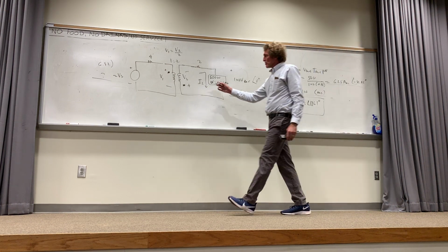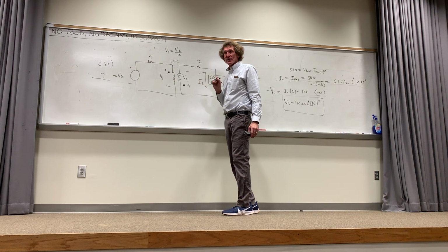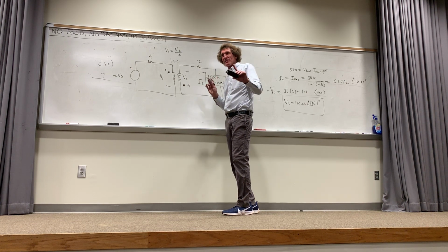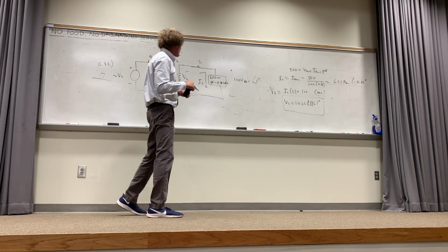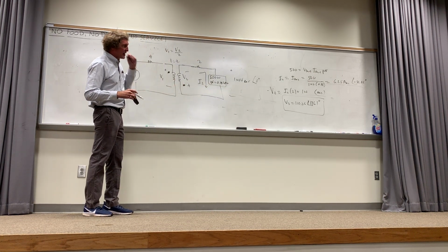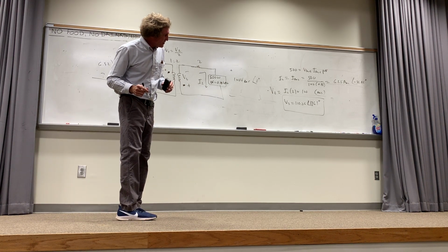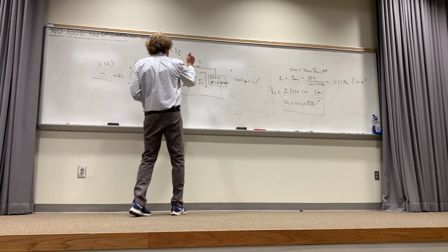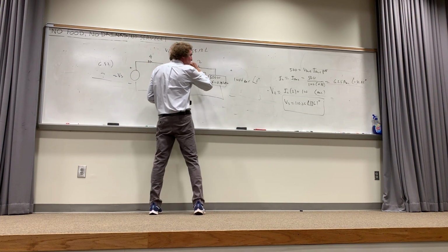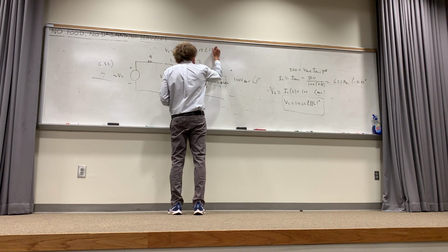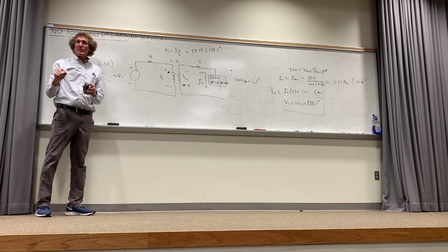Remember, you need the plus to minus voltage of V2. I had the plus here and the minus there, and that's what he does in his solutions, I think, but I'm not absolutely certain. So now that's the right value for V2, and V1 is just half that value. So that's 55.13 at an angle of 176.1 degrees. Agreed? Everybody?